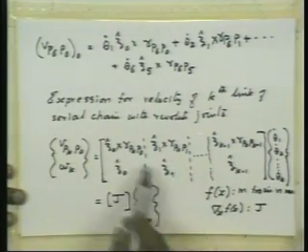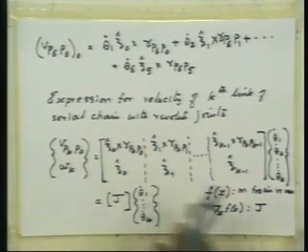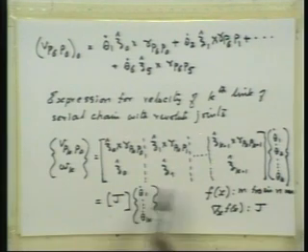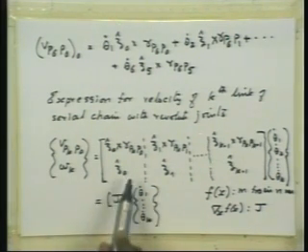Since all this can be obtained by forward kinematics, if you have thetas, you can immediately obtain all this. So you can write the Jacobian very easily. You don't have to go through the derivation which was done right now. All that you have to know is this. And this comes from a very simple physical picture also, right? The angular velocity is simply the sum of the angular velocities you get from these individual rotations.